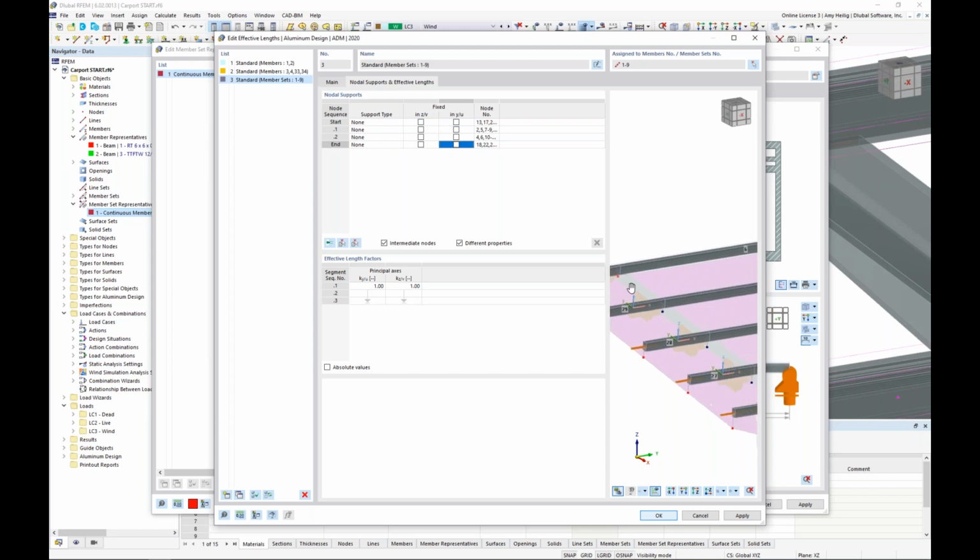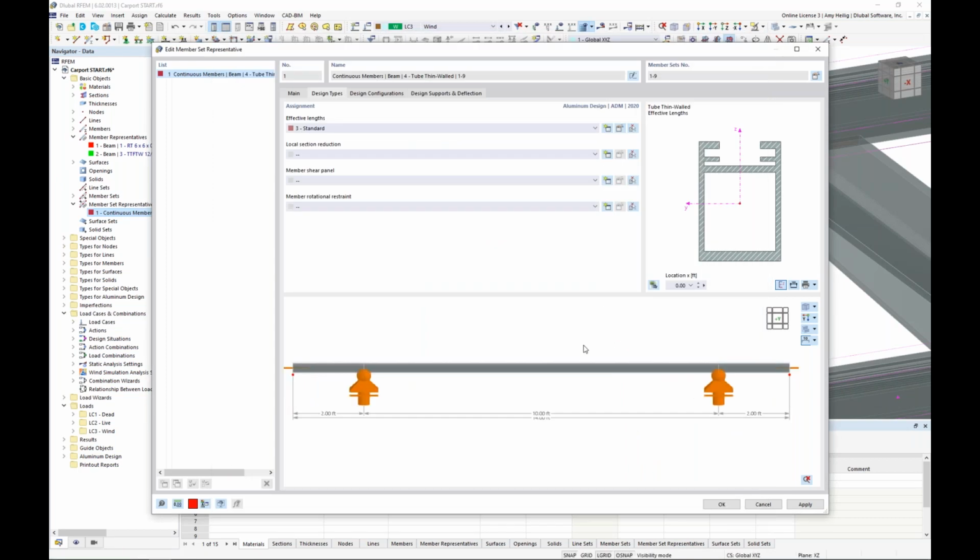But rather, where it frames into the tapered cantilever sitting below it, we'll restrain this element here in both the strong and the weak axis directions. So now we click OK, and what we should see then are intermediate restraints update here to the interior nodes instead.